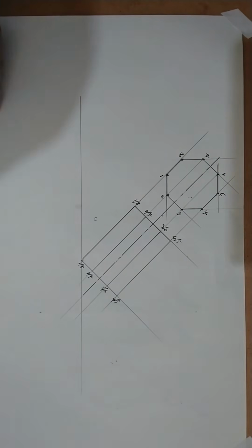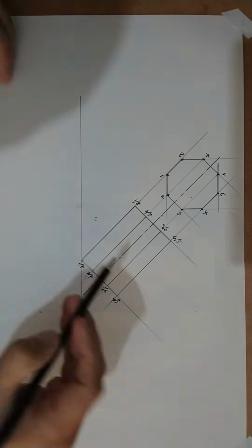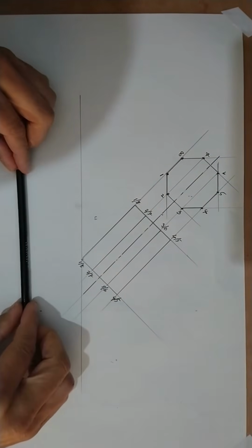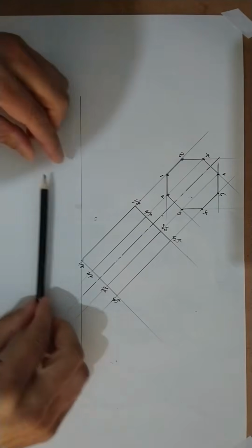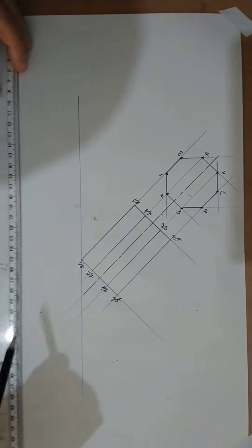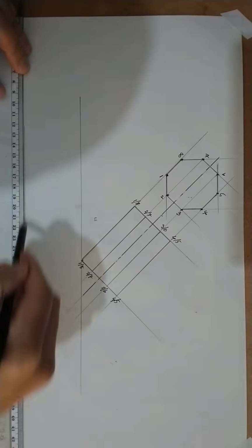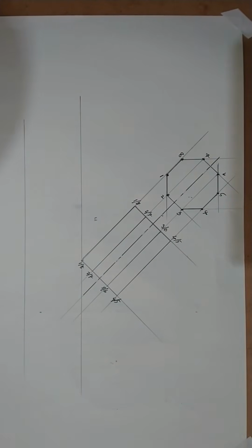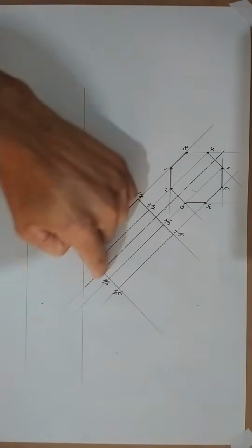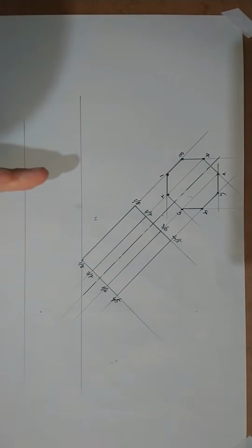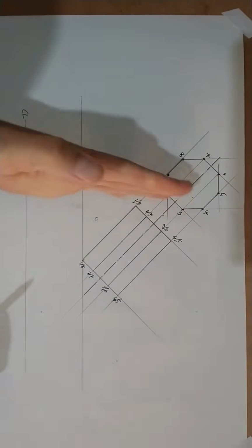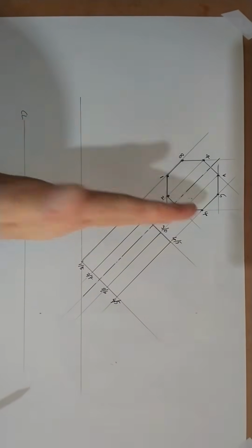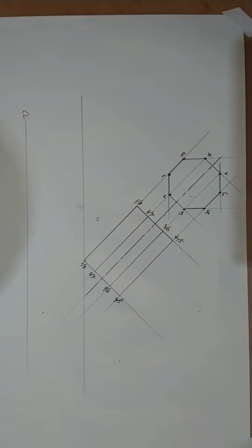The first thing that you need to do is probably to get the center line somewhere around here, right? So you can give yourself enough space. So I'm going to draw a faint center line there, right? There. And that's going to serve as this line here. And now once I've got my center line, I'm just going to write here "center line" just to keep track of that. And then I'm going to project all my points that I have on my top base and all my points on my bottom base. I'm going to project it down.